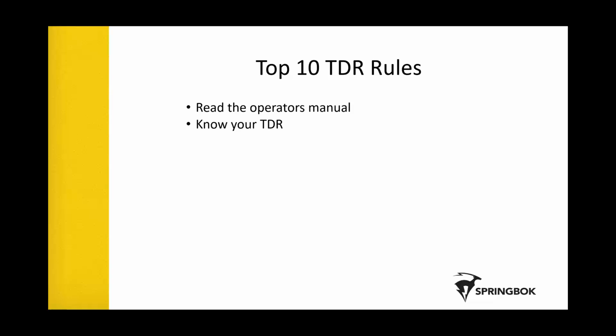Anything that you use, and this applies to all your test equipment, the more you know it, the better you're going to do. And one of the things I like the most about my particular TDR is that, at the very least, if you know nothing, learn to store a waveform, because analyzing stored waveforms later on can get you up to speed so quickly.